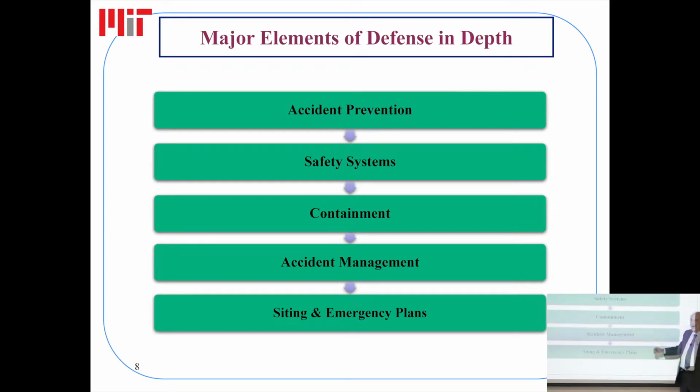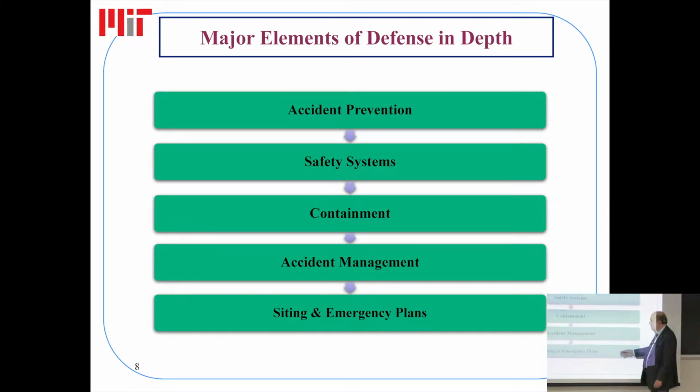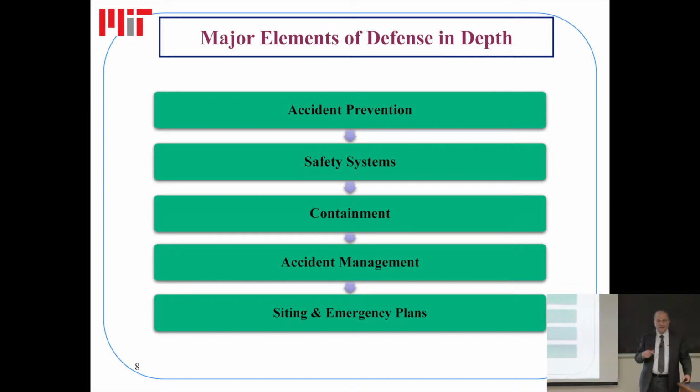And we require accident management. Okay, there are guidelines how to do that and all that. And the ultimate defense in depth is the emergency plans and the siting of the reactor, of course, at the beginning. So, at a high level, this is defense in depth. But then in each box, you also apply defense in depth. That's why the plants are so expensive.